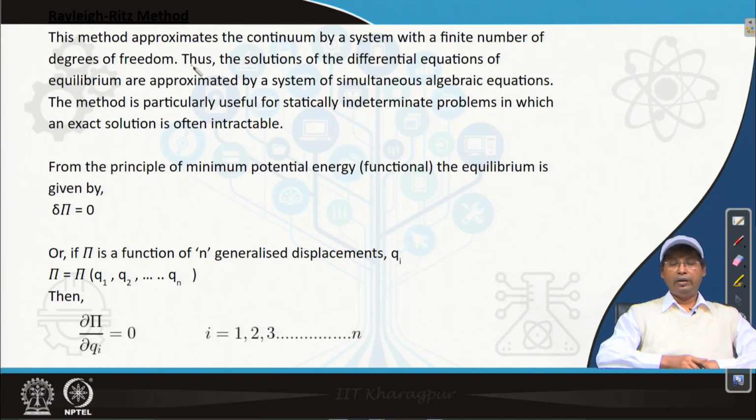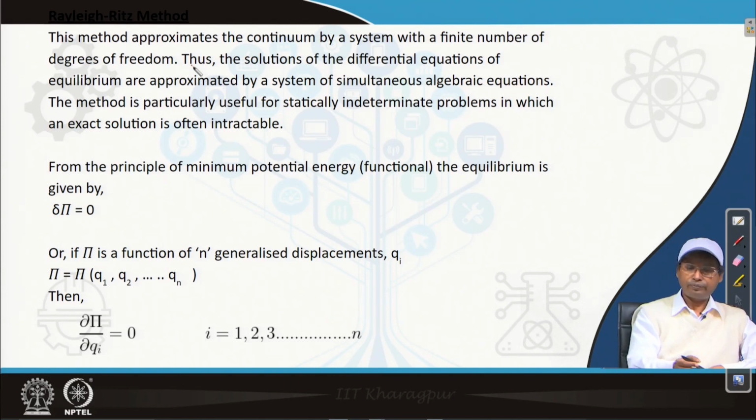In our solid mechanics, we consider the degrees of freedom as displacements, and in general we need to define those displacements as functions and carry out the analysis. So that is the first step. It says that it is an approximate method, because it is divided into a finite number of degrees of freedom. It is not a continuous one.